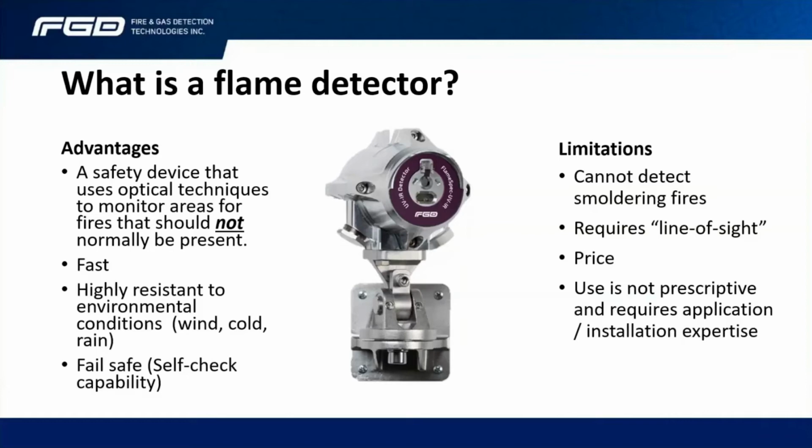What a flame detector can't do, however, is monitor for a smoldering fire or an ember. That falls to the realm of the ember or spark type detector, so that is not a flame detector itself. We do require line of sight, and probably the biggest argument that people will ever say to me is that the products are expensive. Well, you pay for what you get, basically.